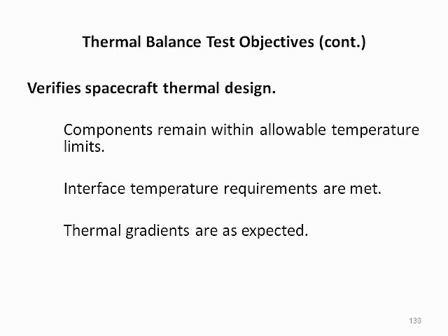The thermal balance test also verifies the thermal control subsystem design by showing that components remain within their allowable temperature limits, that interface temperature requirements are met, and that thermal gradients are as expected.